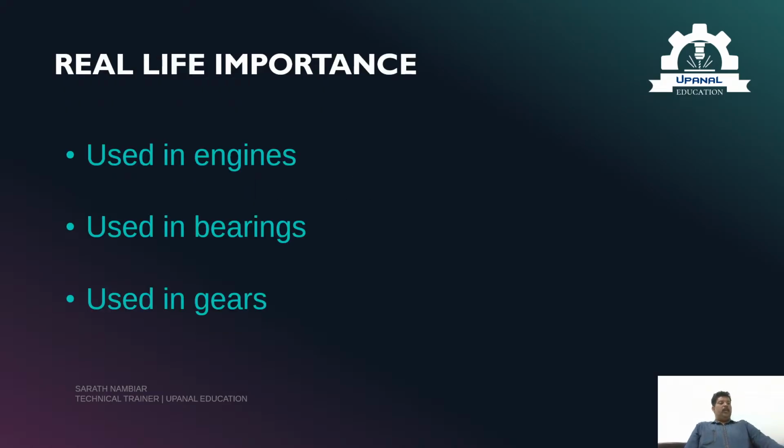Now let's look at where all these concepts are actually used in real life. Fits and tolerance are not just theory inside the textbooks. They exist inside every machine around us. Take a car engine. Inside the engine, the piston moves up and down inside the cylinder. If the fit is too tight, the piston may get stuck and the engine may overheat. If the fit is too loose, gas or fuel will leak and there will be loss in power. So engineers carefully calculate and select the correct fit.